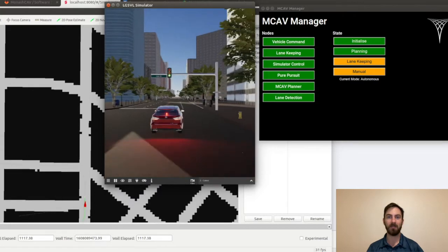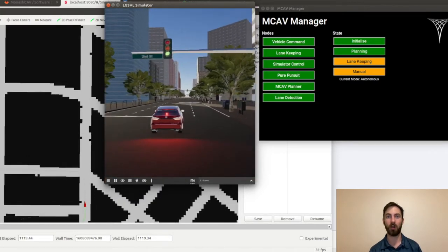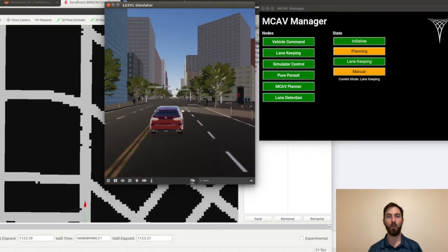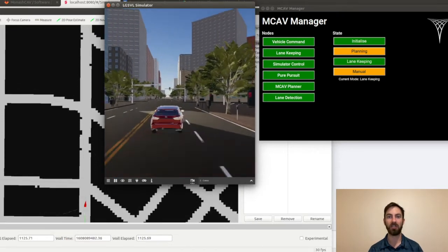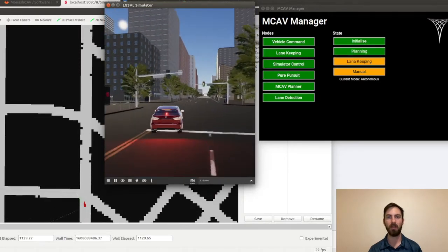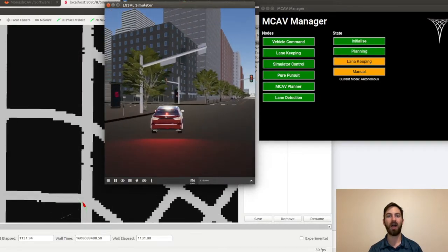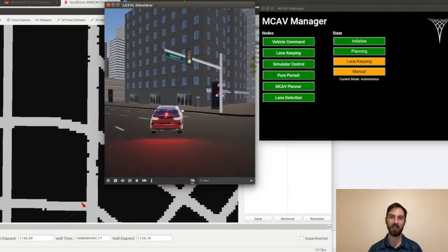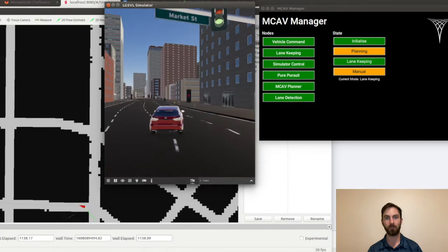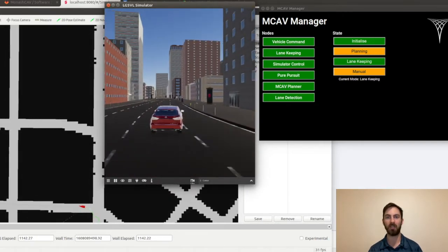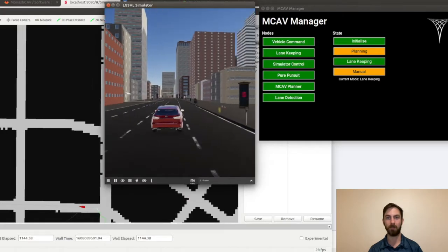The lane keeping system is responsible for control of the vehicle during most of the driving. However, when the vehicle approaches an intersection, as determined by pre-marked locations on a large static map, an algorithm known as hybrid state A* is used to generate a path from one side of the intersection to the other. Once generated, the path is handed over to the pure pursuit package built by the controls team.